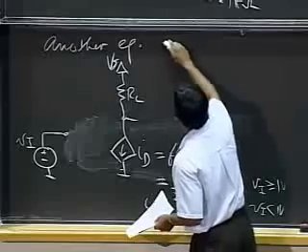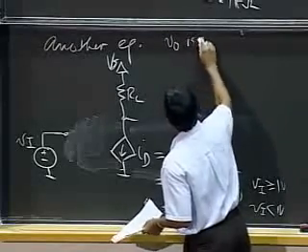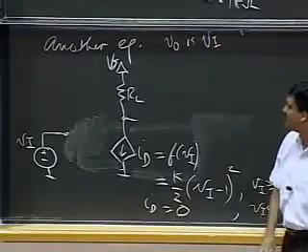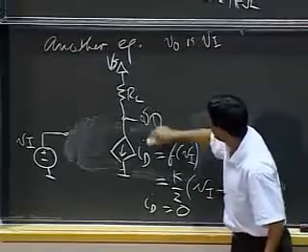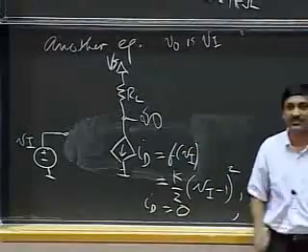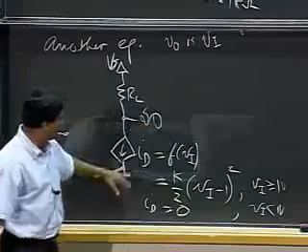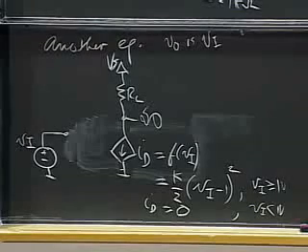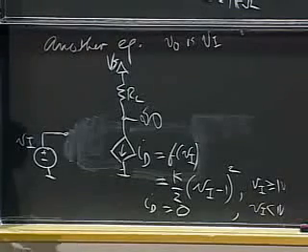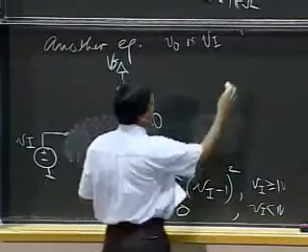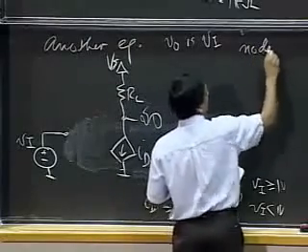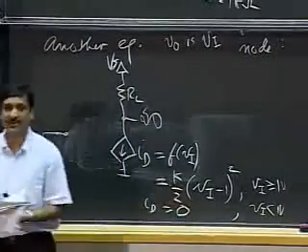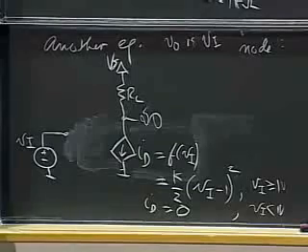So I can go ahead and apply. So let's say I want to find out V0 versus Vi. So I care about finding out V0, where V0 is the voltage of this node with respect to ground. Okay? So it's a slightly more complicated circuit than you saw up there. So let's go ahead and do this example. Start by applying the workhorse of the circuits business, the node method.